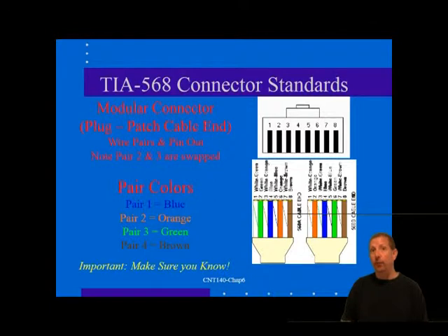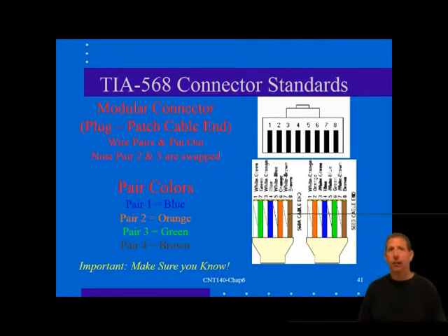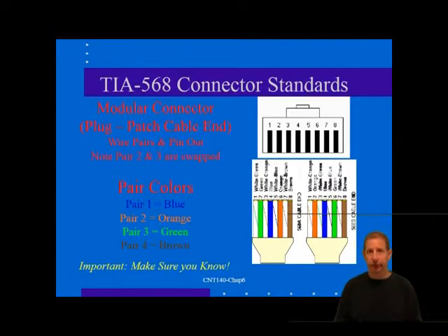A common wiring pattern problem can occur in the horizontal cross-connect. If you terminate the horizontal cable into a punch block first, then cross-connect to a patch, you should be sure that the patch wiring matches that of the corresponding wall outlet, and that you have preserved the pair order during punch down and cross-connect. And we're going to cover that in Chapter 8 when we talk more about patch panels.